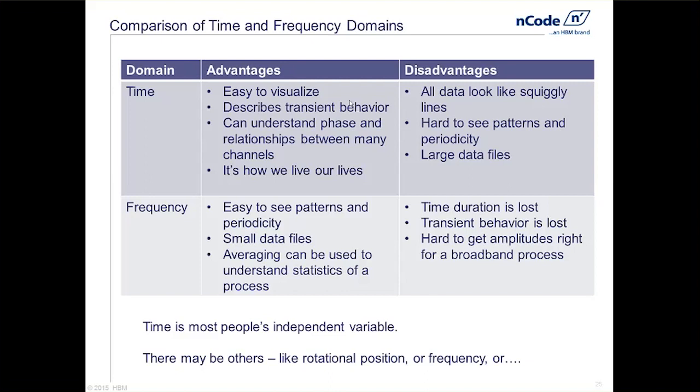If we're looking at a ground vehicle application and we're looking at a speed channel or maybe an accelerometer channel, we can very easily see in the time domain if the vehicle is parked and stationary or if it is traveling over some obstacles or out on a proving ground course. We can look at multiple channels relative to one another and begin to understand the relationship of phase.